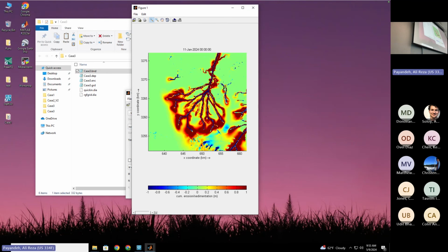And then it erodes the middle, and then it bifurcates. So usually we have deposition at the end of the channels. That's what you can also analyze in the output of case 4 and case 3. And if you compare case 4 with case 3, you see that deposition and erosion is less in case 3 compared to case 4, because case 4 is including mud and sand.